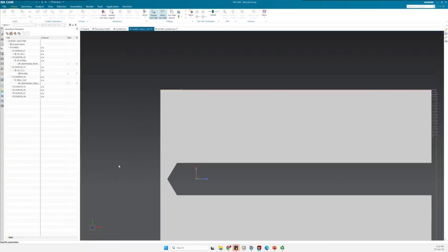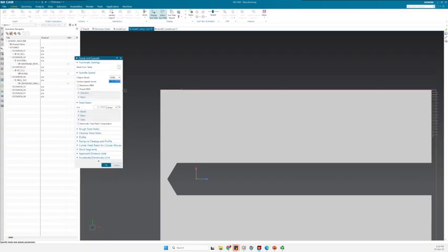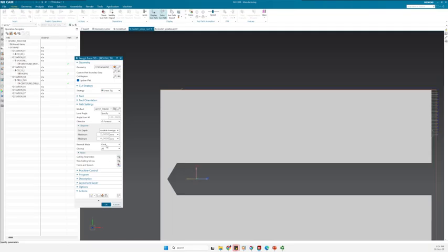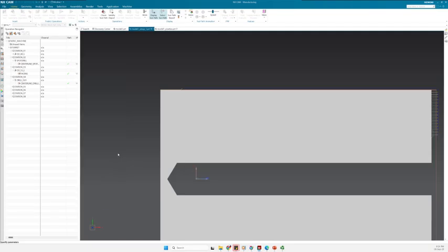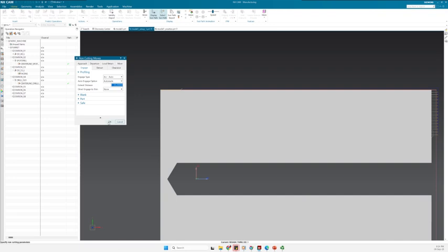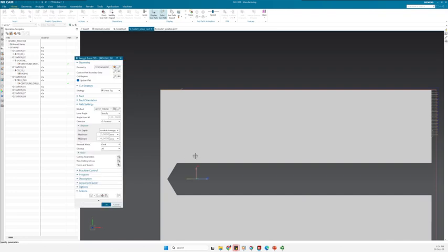Again, similar to the same things, you have the cutting, defining the spindle speed, for example. So again, I will define something here, but these are the things that you need to calculate. Also the feed rate you need to calculate based on the catalog that you have. Then we have also non-cutting movement that we don't need to go through here because there wasn't any issue.